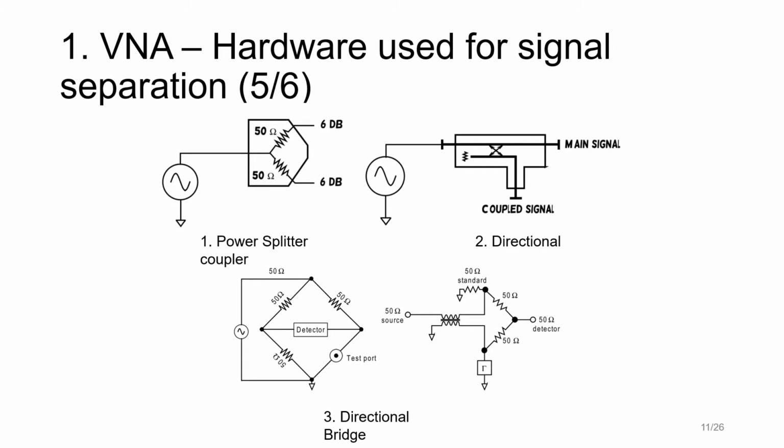Directional couplers we would consider ideal because they have the necessary directional properties. It means that in the forward direction, whatever wave is incident reaches the opposite arm with very minimum loss, and it offers good reverse isolation.